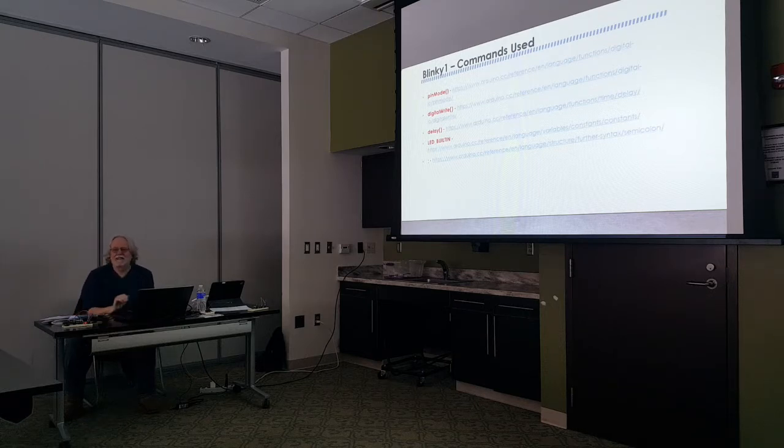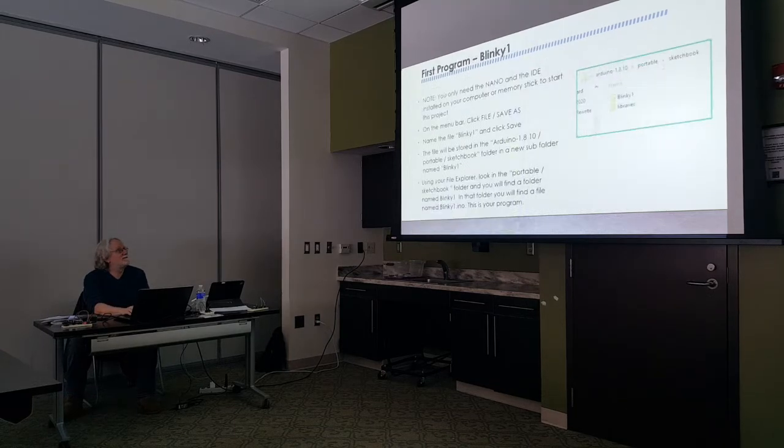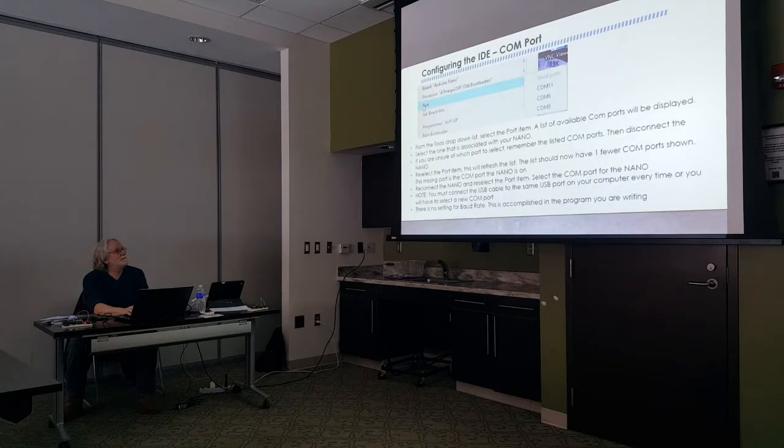So you must compile this against a header, a prototype that's for this particular processor, and the Uno would be a different header file. Correct. See up there where it says board, and the picture of the board, Arduino Nano. Yeah, oh yeah. If you put your cursor on that, there's a whole list of all their boards, and you have to pick the right one. And be careful picking the Nano. I think there's more versions of the Nano than you can shake a stick at.